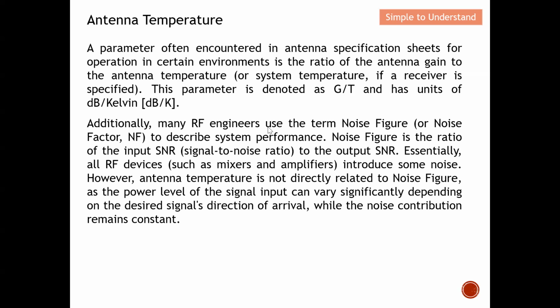Additionally, many RF engineers use the noise figure, or noise factor, to describe system performance. Noise figure is the ratio of the input SNR to the output SNR. This measures the internal noise that is generated. In short, the noise figure is the input SNR over the output SNR.